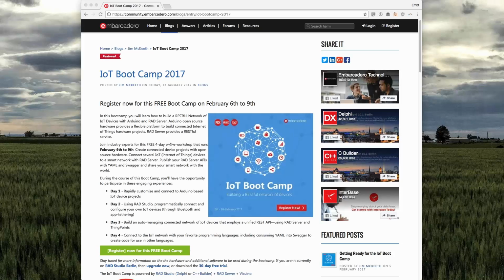Node MCU is another one which is among my favorites. Again, it's small, it's cheap, and it has built-in Wi-Fi, and it has plenty of memory and stuff. The only disadvantage of Node MCU is that it has only one analog pin, and it's not that convenient to use as, let's say, the Arduino pins, but for everything else it's a fantastic board.